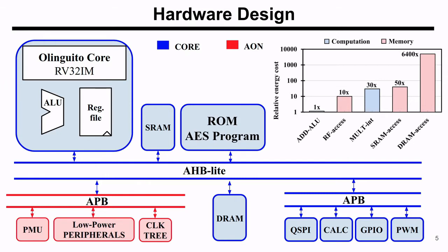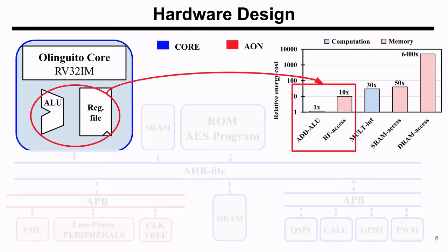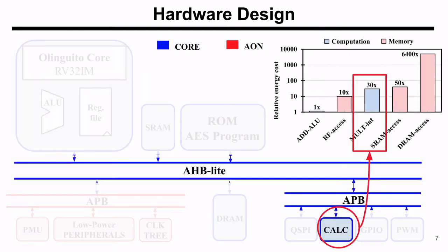In the case of implementing a security system involving AES, we compose the system on chip with a processor, the ROM containing the program, different kinds of memories, and several peripherals. The lowest cost for processing involves only internal calculation and registers within the core. This low cost is due to the short communication paths. However, we'll still need to access the memory to bring the data to encrypt.